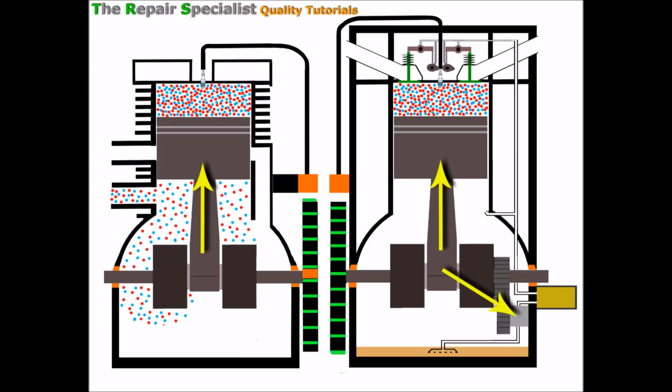The moral of the story is that all the flow and movement in this pipe is created by the pump. Before the oil's distributed round the engine, it goes through this little filter, which filters out all the main impurities to make the oil a little safer to use. Then it's distributed right up along this pipe, lubricating all those vital areas. As we'll see shortly, there's a little nozzle that sprays oil upwards into the cylinder to allow lubrication between the piston and the cylinder.